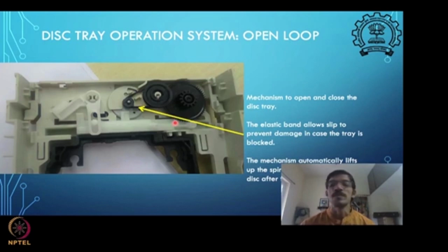So the motor will get burnt if you don't take care of this blocking issue. With the belt, when the output is blocked, the motor is still allowed to rotate, but the belt will slip on the motor shaft.